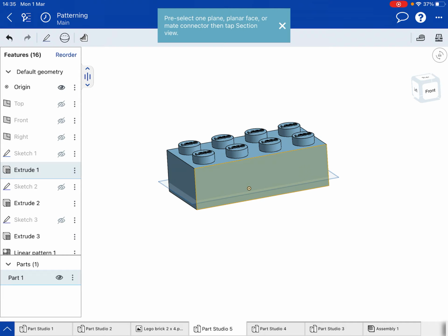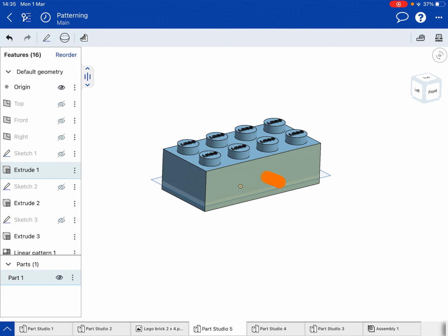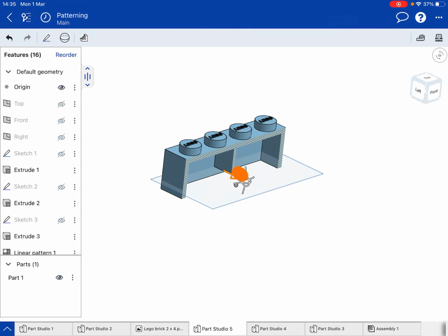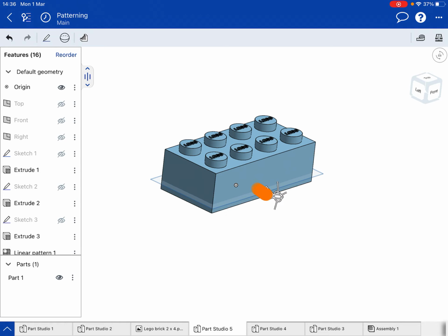I'm going to select this surface here, and that should give me the option then of being able to move this to actually be able to see only part of the surface here. I'm hoping that's actually going to work for this. I haven't tried section view on here before. Section view, yeah, there we are. Okay, now I can move this back. Now can you see that when I take this to the midpoint there, I've got a recess inside that's hollowed out, but nothing has happened on the inside of each of these circles here, which isn't what we want. We want to have a hole through that, but we couldn't shell that out normally, so we're going to have to try and actually indent that in.